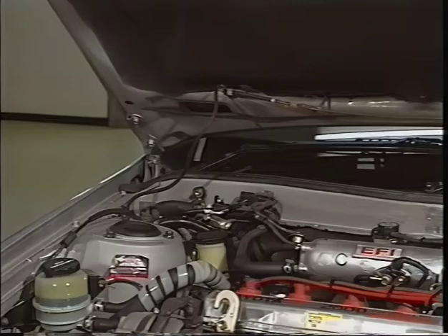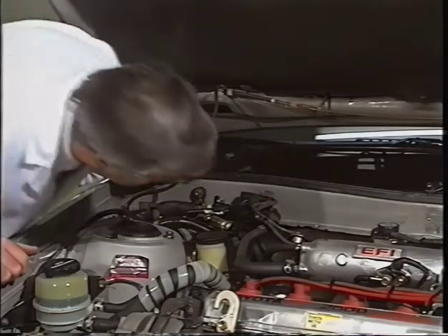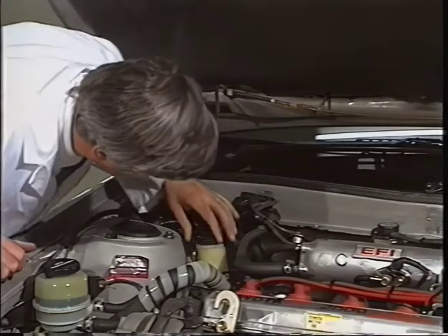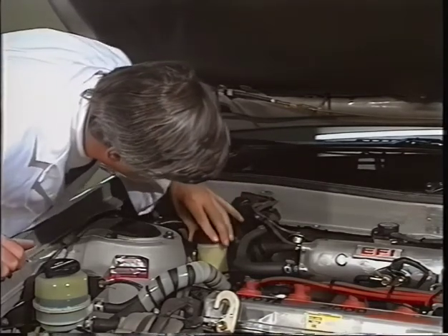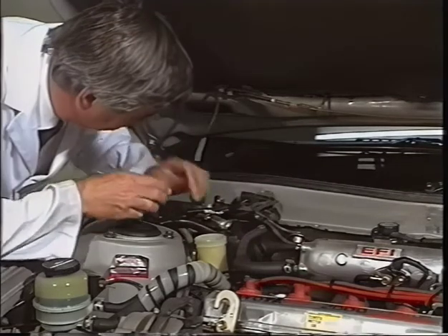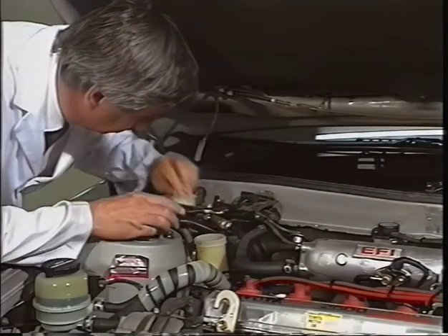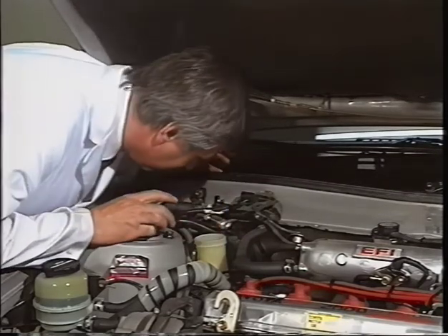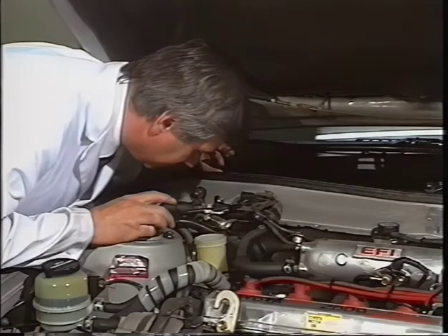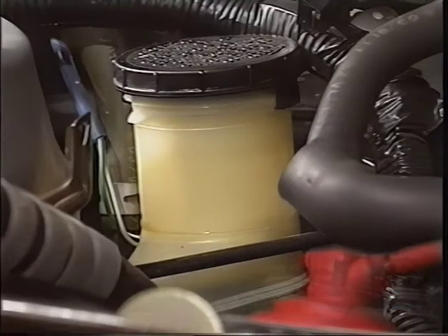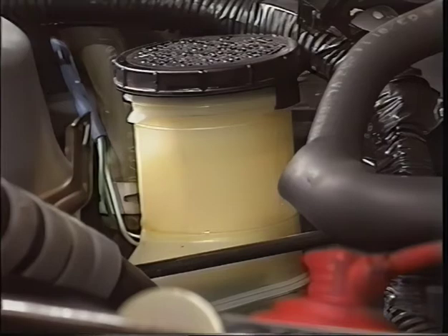Once it's been confirmed that the pedal is indeed low, the next step is to check the fluid level in the master cylinder reservoir. A low fluid level is an indication that a leak may exist in the system, the cause of which must be investigated before proceeding any further. A total loss of fluid in one section of the reservoir would indicate a circuit failure and should have been accompanied by the brake warning light being illuminated.